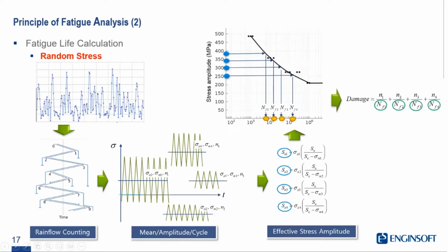We've got the damage from the first input cycle, the second, third, on to infinity. Because this has been linearized, it becomes easier to combine those back to a total fatigue life. So essentially, this is what the software is doing behind the scenes, but it's a very tedious process. It's nice that we have computers doing it for us. And at the end of the day, this is the output that we're interested in.